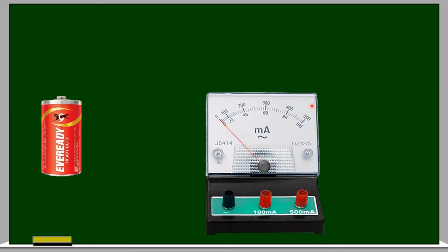The same I am showing here by using an ammeter how current decreases in the circuit when a resistor is connected in the circuit. So here is the dry cell. Whatever the circuit I have taken previously, the same circuit here I am taking. The only thing is that in place of bulb I am going to connect ammeter, that is milliammeter, here I am using.